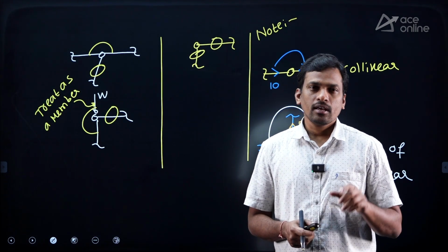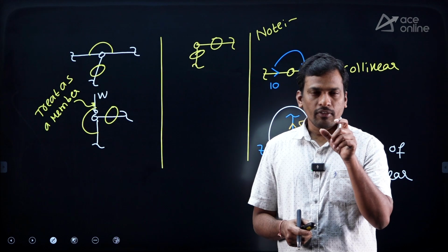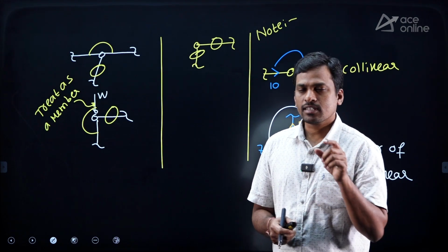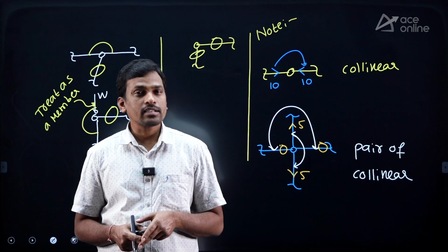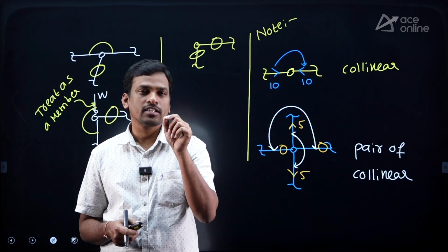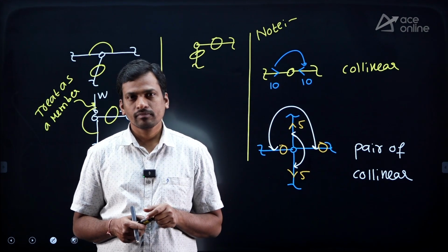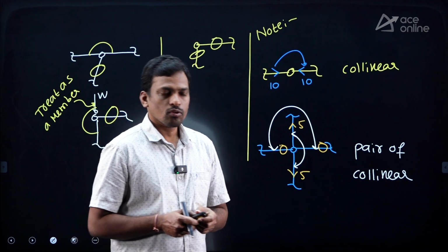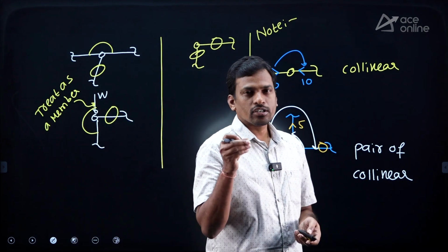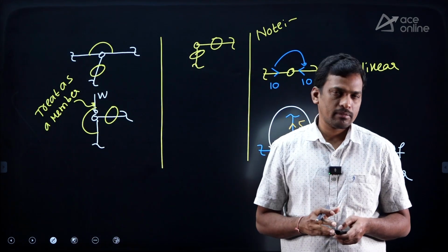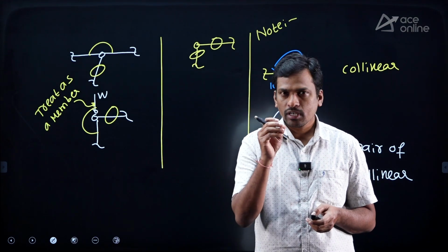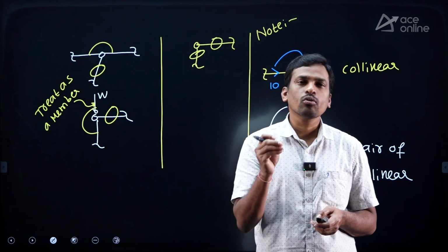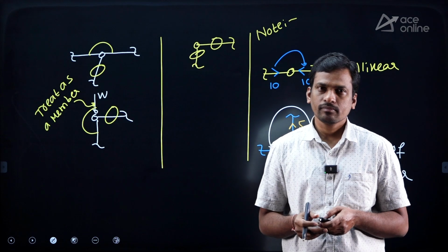So students, I repeat, if you use method of section, it depends completely on only these 2 conditions. In the class notes, I gave 5 stars for this point. Yes or no? First condition: the section should pass through the selected member. Second condition: the section should divide the entire structure into 2 separate parts.